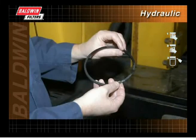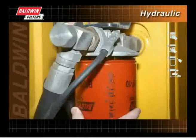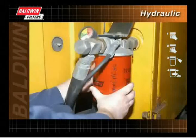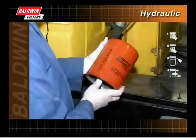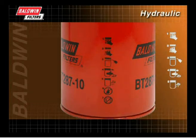Apply a thin film of clean fluid to the filter gasket. Do not use grease. When installing a Pure Force hydraulic filter, the threads also need to be lubricated before installation. Line up the threads on the filter with the threads on the mounting base carefully to avoid cross-threading. Screw on the new filter until the gasket comes into contact with the base. Follow the instructions of the filter manufacturer for final tightening. The pictogram on the filter will tell how many additional turns from gasket contact the filter requires.